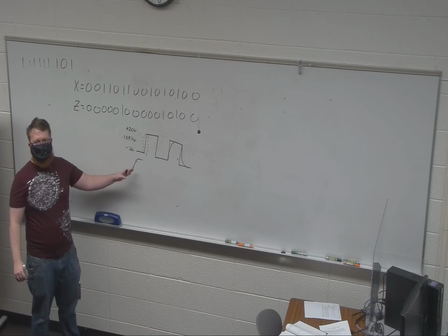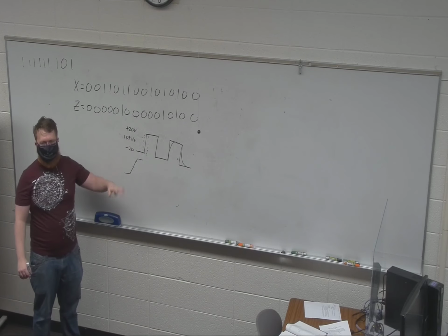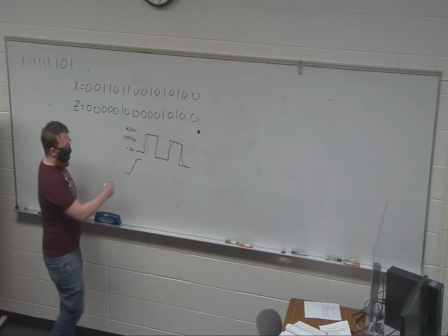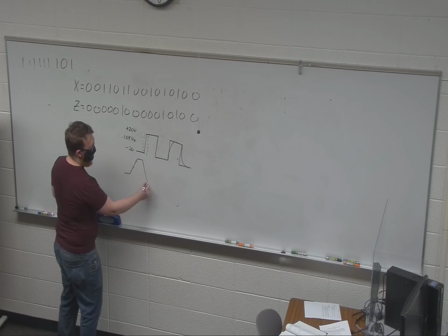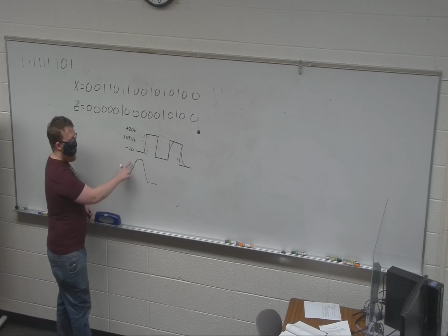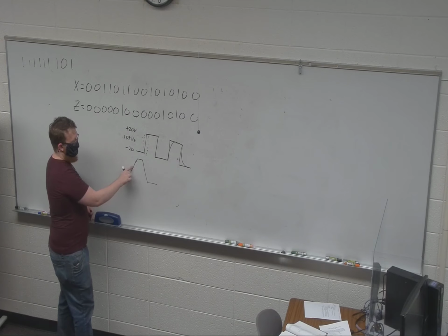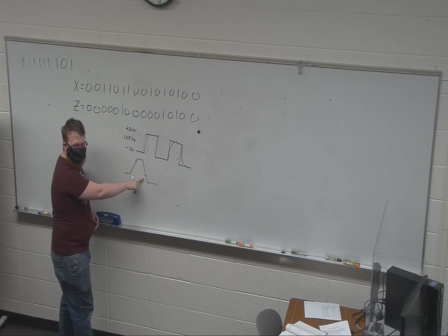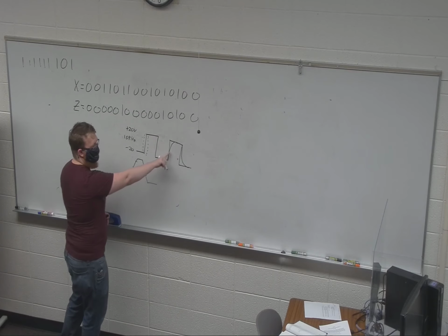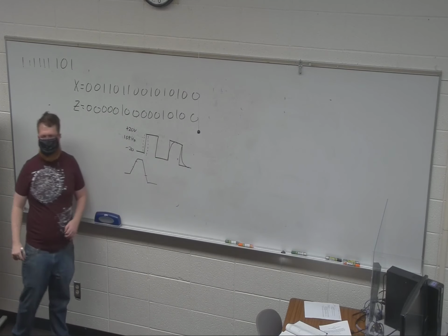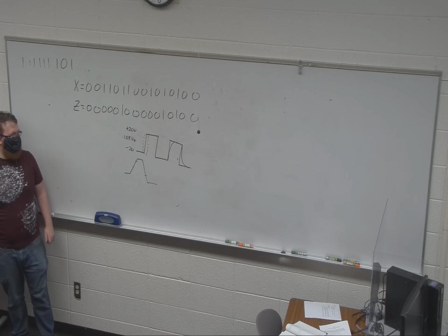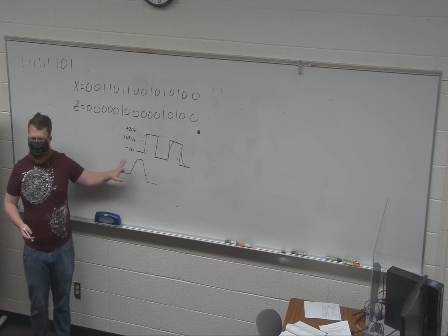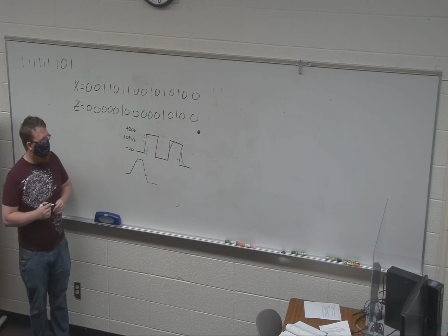And there is very often directionality to when it's changing. So on the upswing, it'll change from 0 to 1 at, say, that trigger point, but then on the way back down, it won't go back to 0 till here. And so if your clock is irregularly shaped due to excess capacitance, your timing can get really screwy.